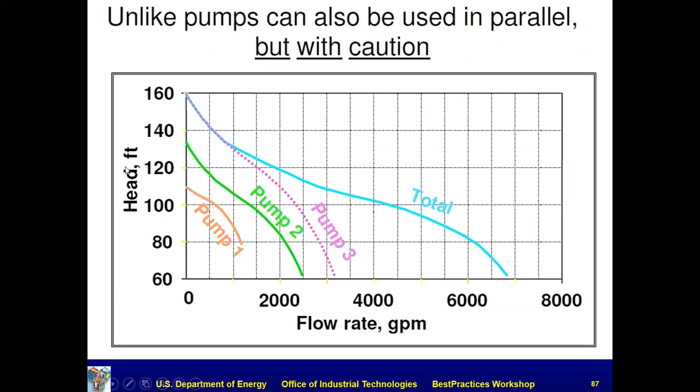So, what do you do? Well, it's the same theory, but you have to realize that, for example, this pump number 1, about 110 is its shutoff head. If the pressure it's trying to discharge into is greater than this, it's not strong enough to push any fluid out. And so it's what we call deadheaded, and it's basically a water heater. And if you run it real long, all that energy can't escape from the pump, and you're going to vaporize the fluid, and it's going to start boiling in there, and eventually you're going to tear up the pump, okay?